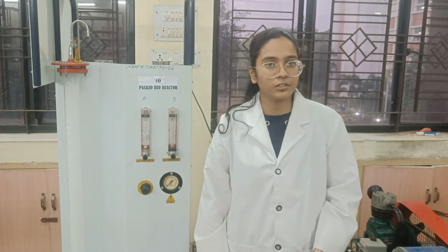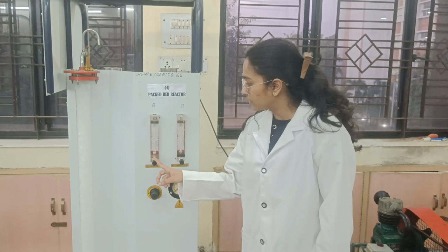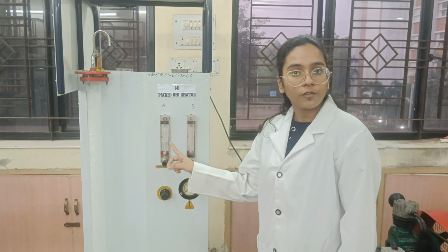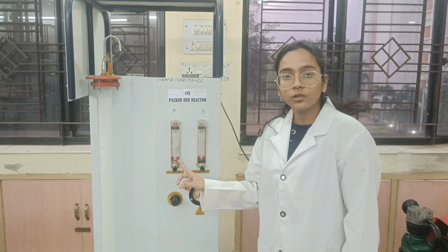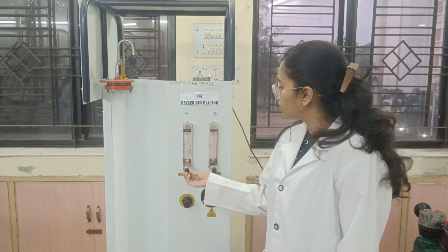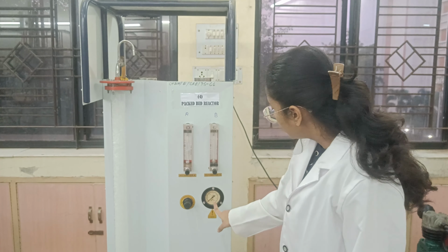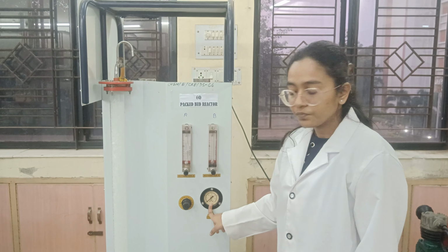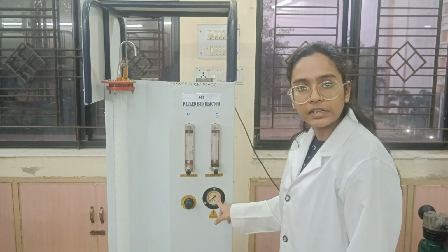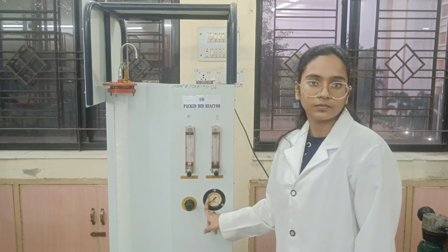While conducting the procedure, we need to take precautions, as sometimes the flow rates of the rotameter drop or rise. We need to keep a watch that they do not rise or fall, and if they do, we have to adjust them back to their original flow rate. Also, the pressure gauge mostly increases. We have to make sure that we keep it back at 1 kgf.